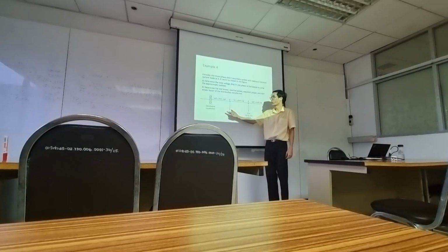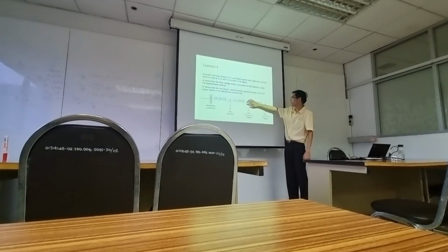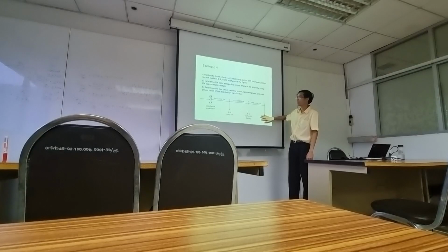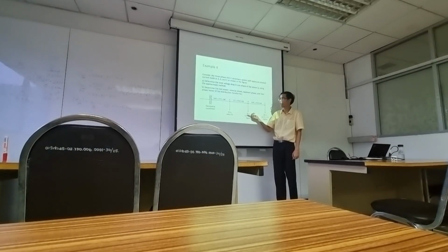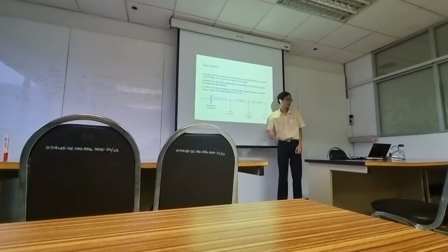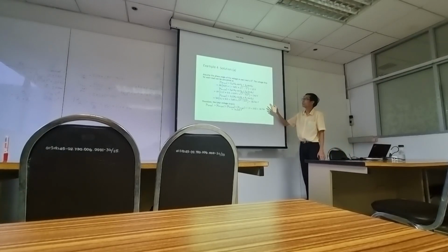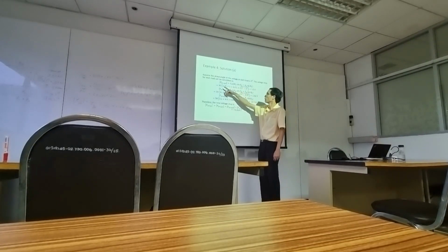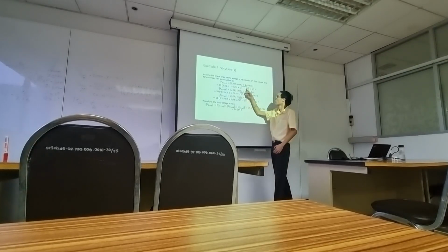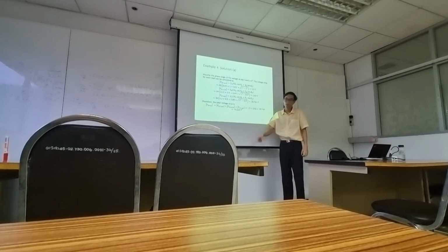First, we calculate the voltage drop due to load A, and we don't care about B and C at all. After that, we calculate the voltage drop at load B; we just take out A and C. So this is the voltage drop due to load A: IA is 30, RA cos theta A, plus XA sine theta A. What is R and X?